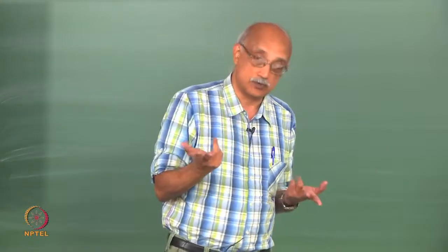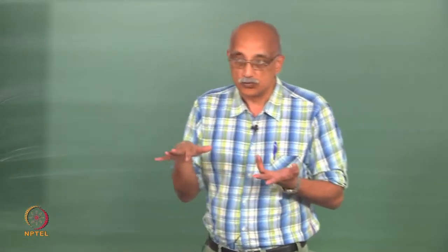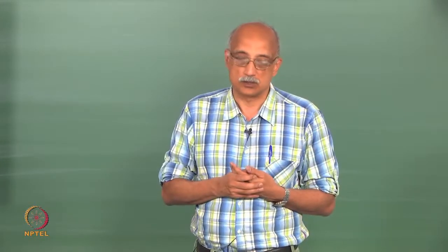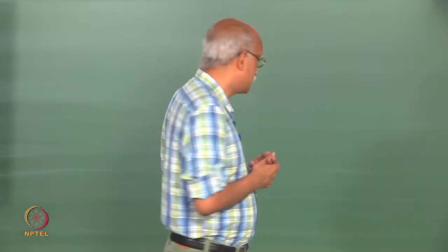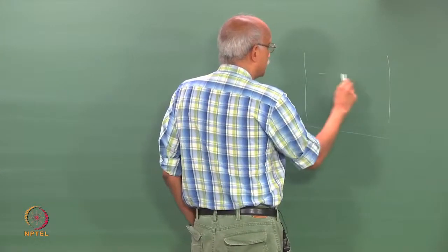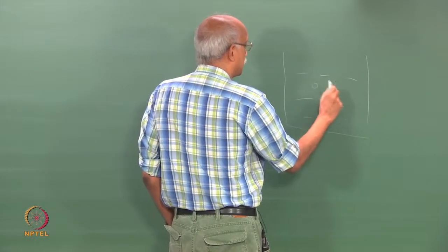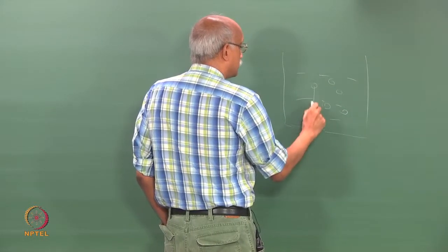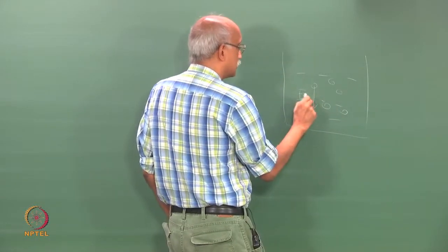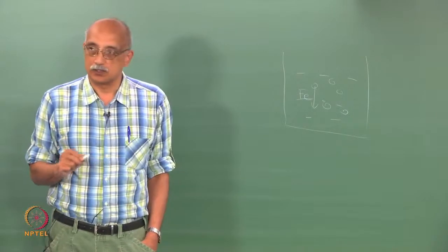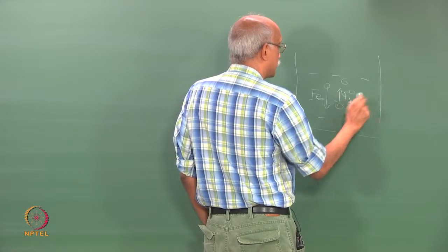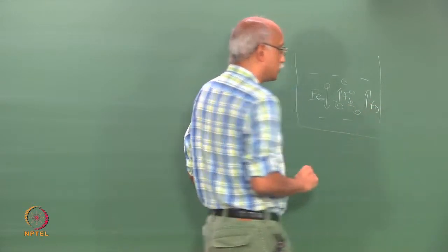Electric forces, thermal forces can induce thermophoretic velocities, magnetic forces if you have magnetic particles in your system and so on. But in general, the picture is you have a fluid and you have particles that are moving through, and so there is a force, let's just call it some Fe, external force, which is opposed by a buoyancy force and a drag force.